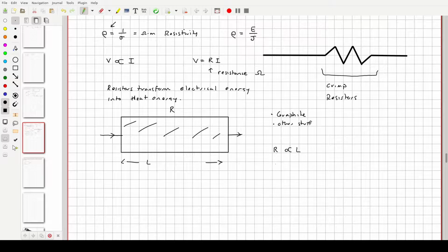The relationship between area and resistance is 1 over the area, for what we call linear materials, which is what we like most resistors to be. So your resistance is proportional to the length of your resistor and 1 over the area of it. If you follow this through, the physical definition of resistivity is that constant that sits in front to handle this.